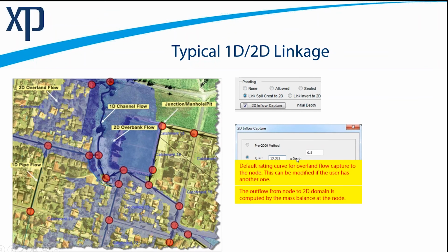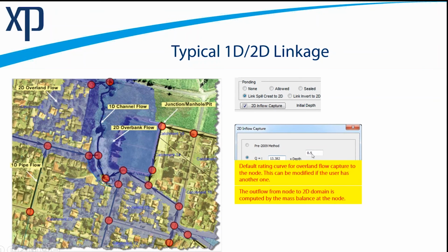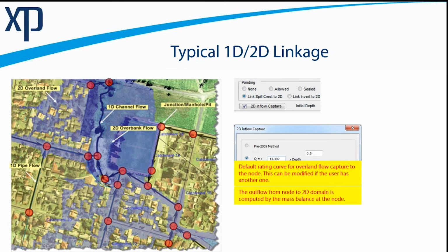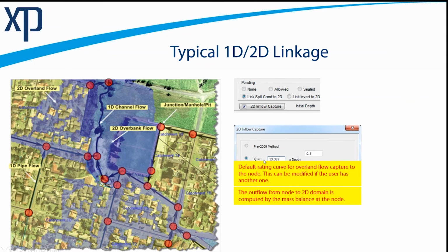Now this is a classic hydraulic equation. With an exponent of 0.5, this represents an orifice. If the exponent is 1.5, which clearly you can enter because it's a user field, at 1.5 it's more like a weir. And then the size of this coefficient is really related to the size of the opening. So you're putting in here, for example, if you wanted to model orifice, orifice area, orifice coefficient, etc. So this is a generic equation, but it fits weir and orifice very easily.